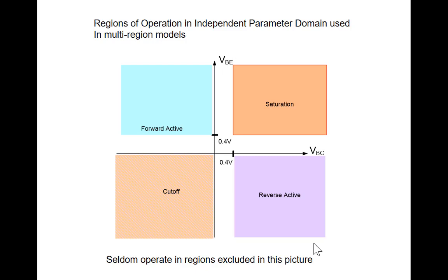Mr. Strong. They flatten out. They pretty much stay constant. No. If that was the case, it'd be good. The current is equal to something e to the VBE over VT. What happens when the base emitter voltage gets much above 700 millivolts? It will just exceed the rating of the transistor.